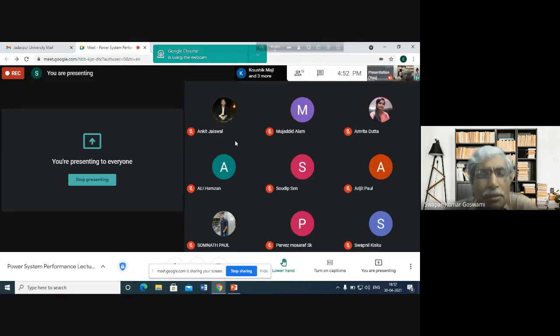Aluminum has low tensile strength, so all aluminum will have a lower tensile strength. That's why in an ACSR conductor you will have a number of conductors together, where the innermost conductor will be a steel conductor. Sometimes where more strands are added, then more steel conductors may be added together. So this is the stranded conductor.